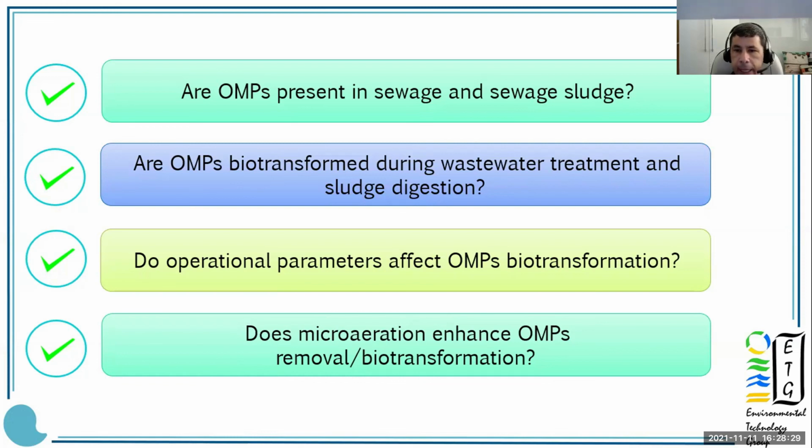The methanogenic activity matters in sewage, but not in the digesters. The chemical structure, yes. The hydrophobicity, yes. But combining hydrophobicity, for instance, triclosan is a very hydrophobic compound, therefore very well adsorbed into the biomass, but it is not further biotransformed, being a very stable compound for microbial biotransformation under anaerobic conditions. And thus, does microaeration enhance OMP removal by biotransformation? We showed that yes.